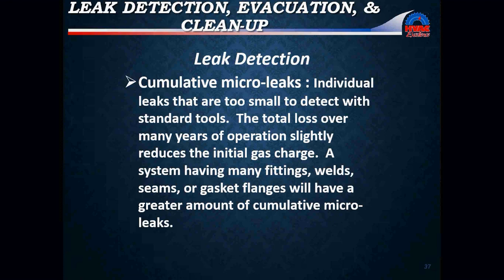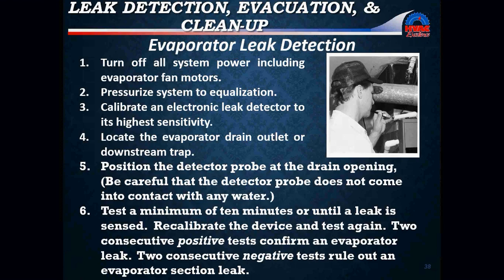Oil may not be present with micro leaks. Oil may not reach certain leak positions. Oil may not be present on new startups. So we have to be very vigilant when it comes to leak detection.